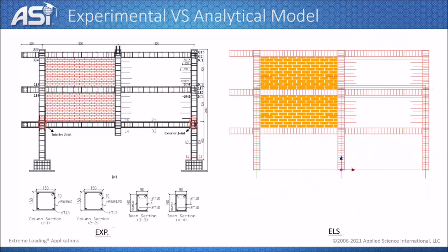Let's begin here by showing a verification example, a way to verify if the ELS is working in a good way or not. So basically what we have in here is an experiment that was done in the lab for a 2D reinforced concrete frame with infill walls, and these infill walls are connected to the columns using dowels, as we see in the pictures in here.